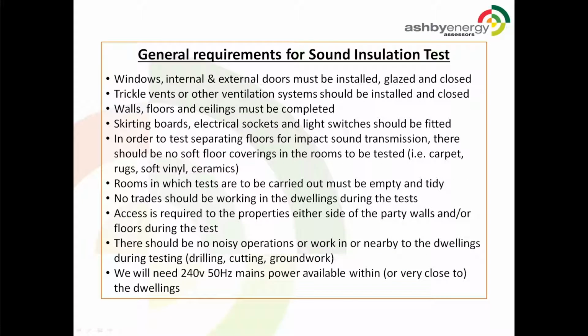General requirements for sound insulation test. Windows, internal and external doors must be installed, glazed and closed. Trickle vents or other ventilation systems should be installed and closed and switched off. Walls, floors and ceilings must be completed. Skirting boards, electrical sockets and light switches should be fitted. In order to test separating floors for impact sound transmission, there should be no soft floor coverings in the rooms to be tested, i.e. carpets, rugs, soft vinyl ceramics or any kind of cosmetic flooring.